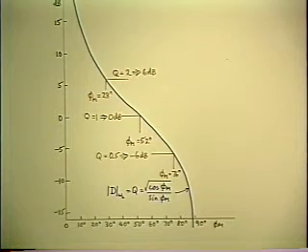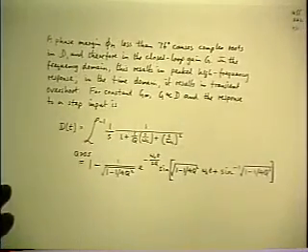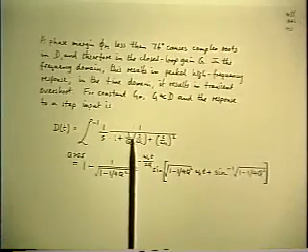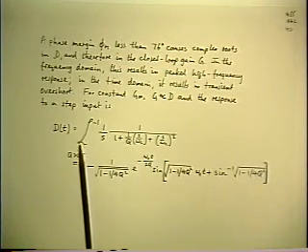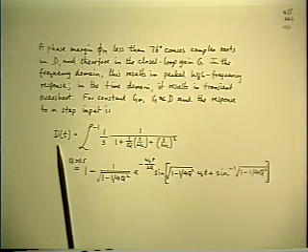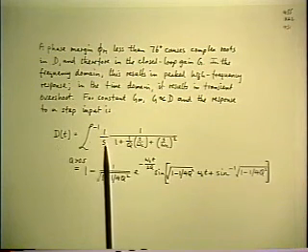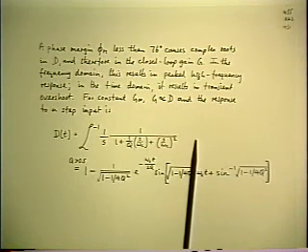So there's a corresponding result, which in fact was brought out at the beginning of all this, which arises when you consider that the transient response of your system also is influenced by the phase margin, and for the same reason. The way you look at transient response is, if you have a step function applied to the front end of your amplifier, then you find the transient response of its output voltage by taking the inverse transform of the step, which is 1 over S, times the transform of the gain of the system.